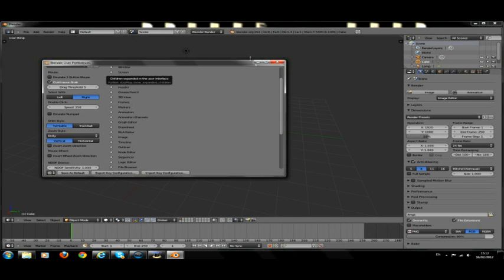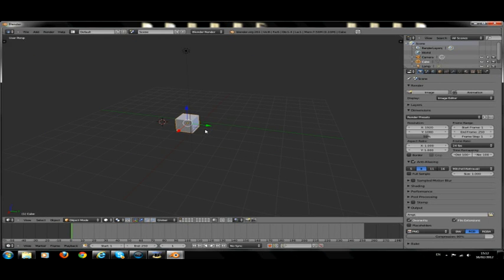Now, that's the way you orbit something. When you left or middle mouse click, you can orbit and change the view. You orbit a virtual point in front of you. The trackball keeps the actual rotation of your view, so if you rotate it around that way or this way, it doesn't change, whereas with trackball, you can actually rotate around that way and that way.